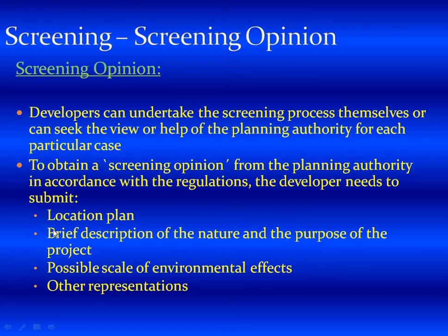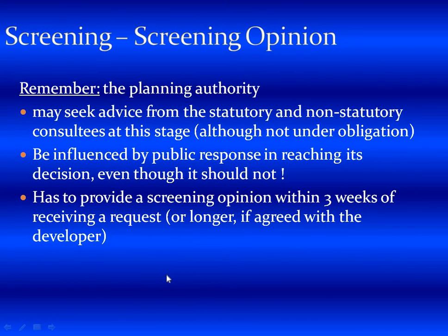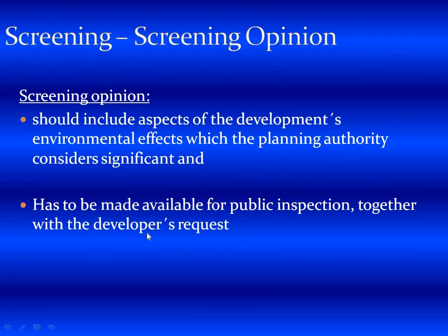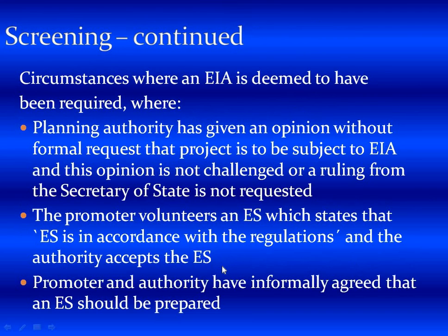Then what are screening options? You have to obtain a screening opinion. What is a screening opinion? It includes a location plan, a brief description of the nature and purpose of the project, the possible scale of the environmental effects, and other representations as required. Planning authorities may seek advice from statutory and non-statutory consultees at this stage, and may be influenced by public response in raising decisions. They have to provide a screening opinion within 3 weeks of receiving the request. Screening opinions should include the aspects of the development and the environmental effects which the planning authorities consider significant, and have to be made available for public inspection together with the developer's request.